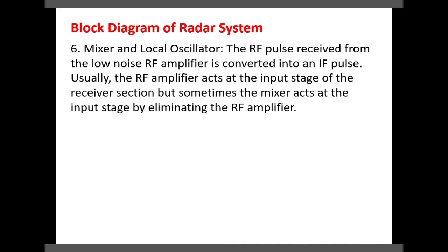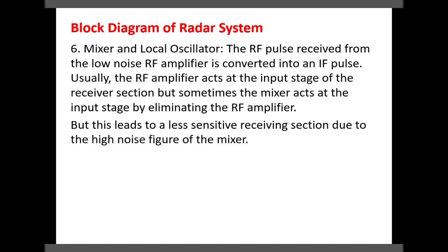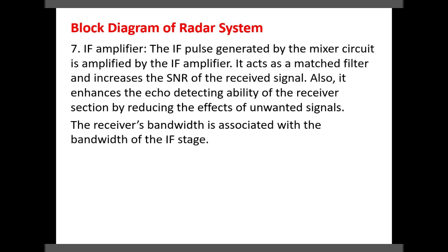Usually, the RF amplifier acts as the input stage of the receiver section, but sometimes the mixer acts as the input stage by eliminating the RF amplifier. But this leads to a less sensitive receiving section due to the high noise figure of the mixer. So this mixer converts the RF frequency to the IF frequency. We are scaling down the frequency so that the operation will be simple and less costly.